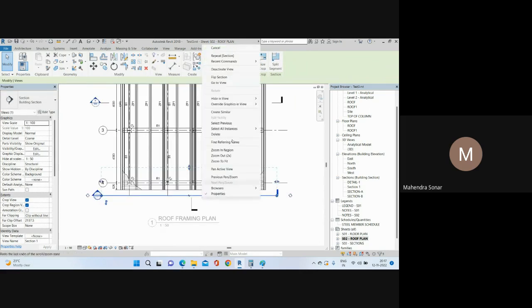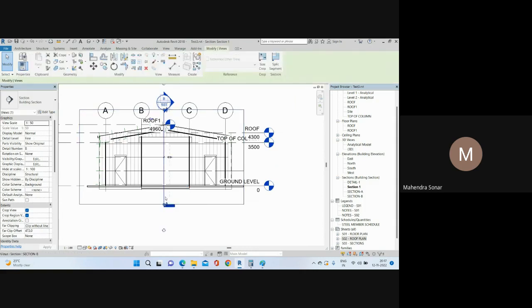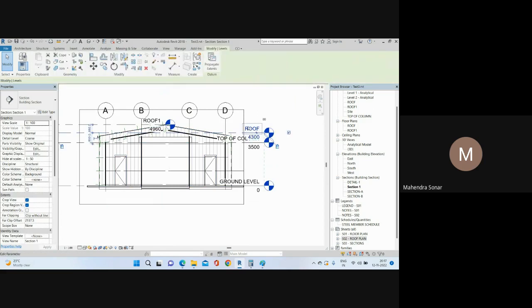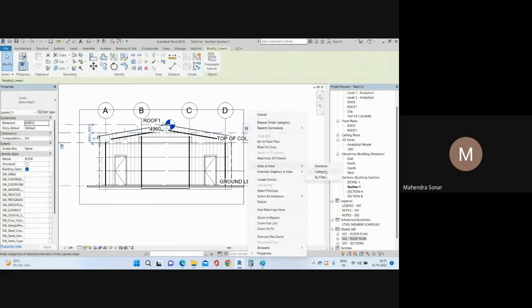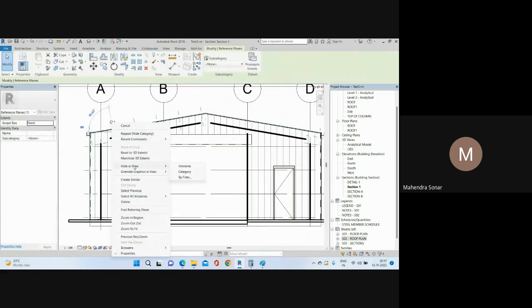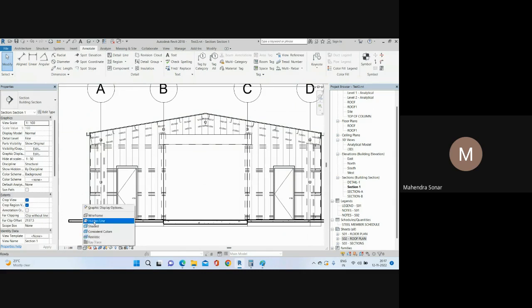And if I go to view, so this is your elevations. So you need to clean up all of this. You need to turn off your labels, then the reference lines you can turn off like that, and then you need to turn on your fine view and hidden lines, right? That's okay.